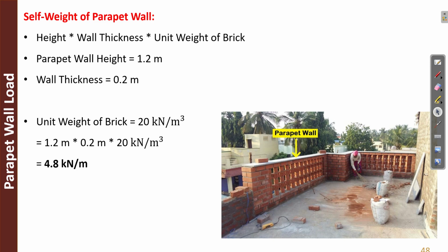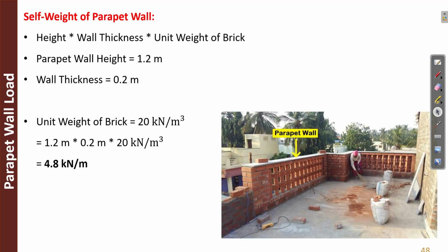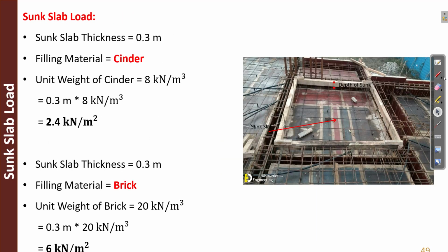So next is sunk slab load. Where will you provide the sunk slab? For toilet areas, we provide the sunk slab. Assume the sunk slab depth is 0.3 meter.